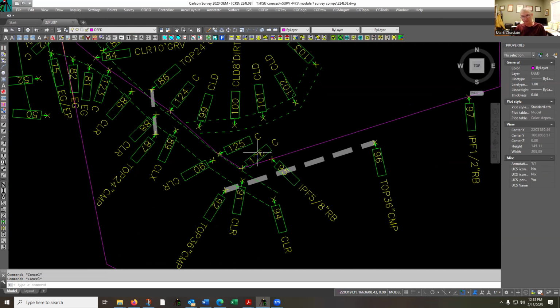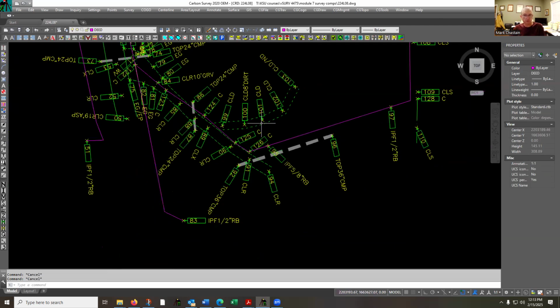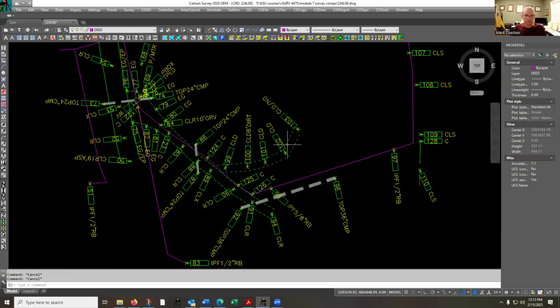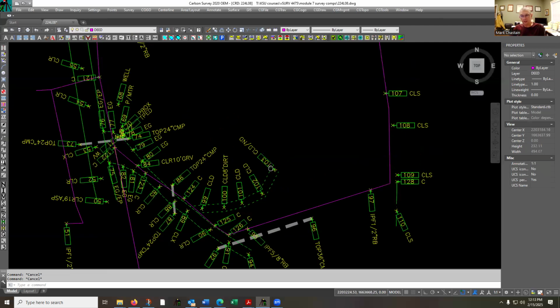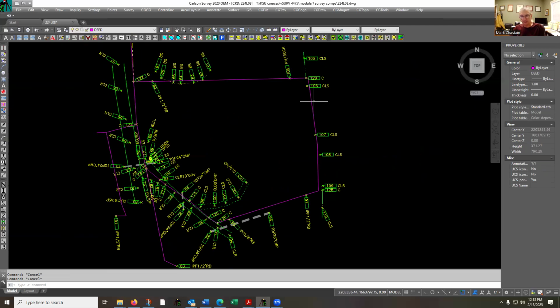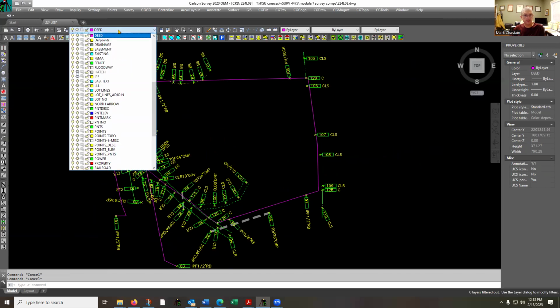And then the people to the south developed that, smoothed it, shaped it, got a better grade, got it to where they liked it, and that horizontally moved where it falls on the ground. That is not uncommon. Again, the rear property line, the east boundary, is the center line of Fawcett Creek. It is a riparian boundary. So where our predecessor located it is nice to know, but we are not going with that. We're going with the creek as we've located it.